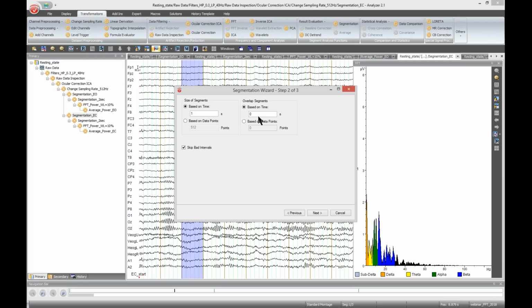So that is the difference and benefit of computing power density with respect to power. To repeat, if you are comparing conditions, power density takes out the effect of differences in frequency resolutions, because it computes power in the same way as normal power, and then normalizes it by the frequency resolution. I hope that makes it clear now.